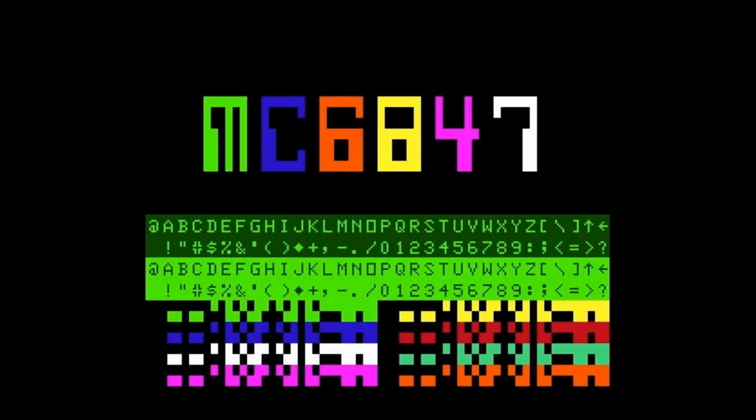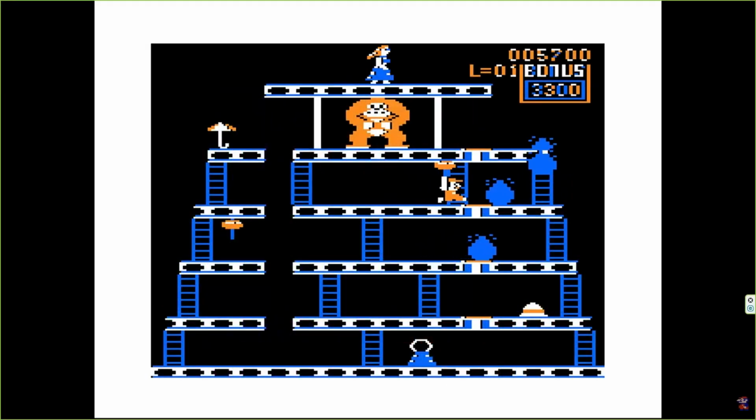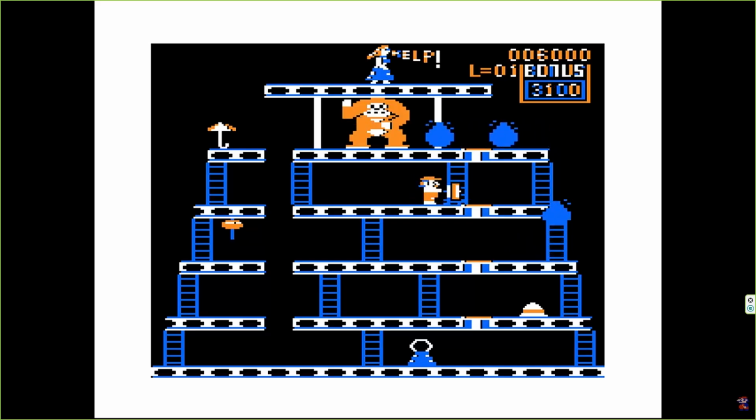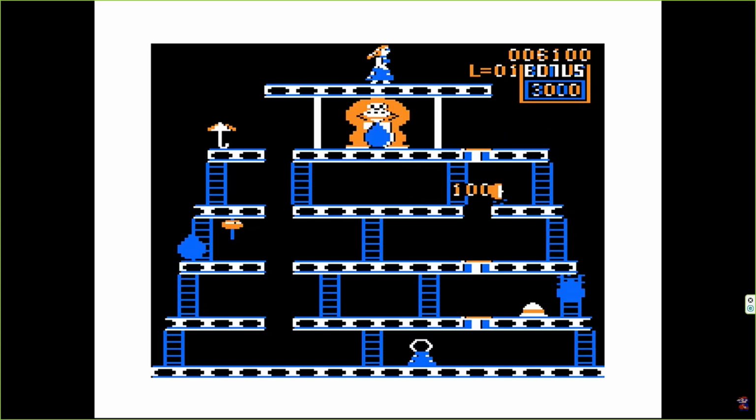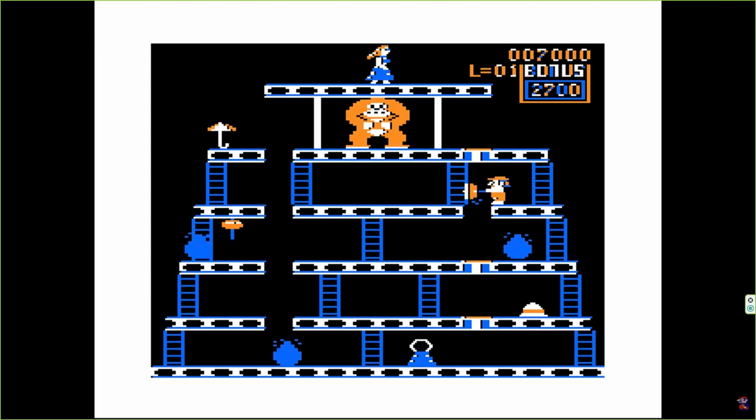The 6847 is more than a little odd in that it generates 12 different colors. Things get trickier in that there are 4 more colors generated in NTSC due to video artifacts. Those video artifacts only work in one specific mode, depend on which clock phase the color carrier signal is using when the color burst is generated, and you can only get 2 of them without doing some electrical gymnastics.